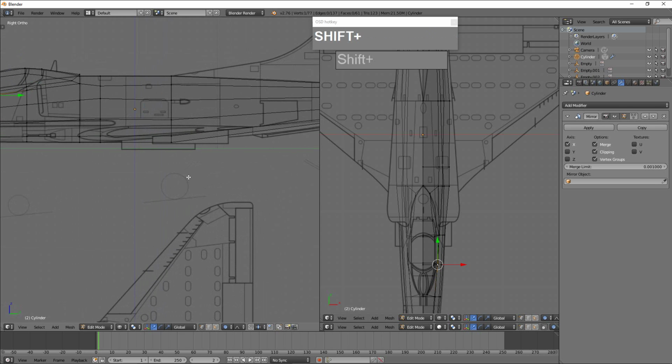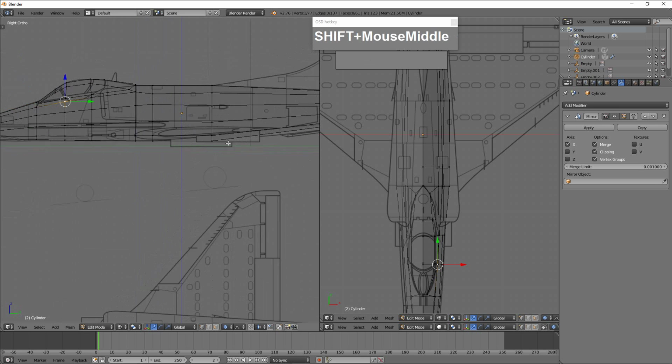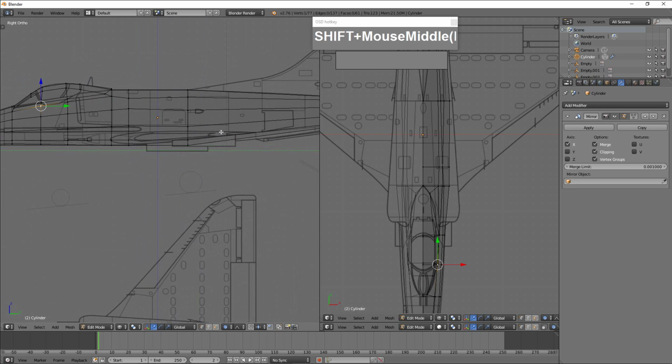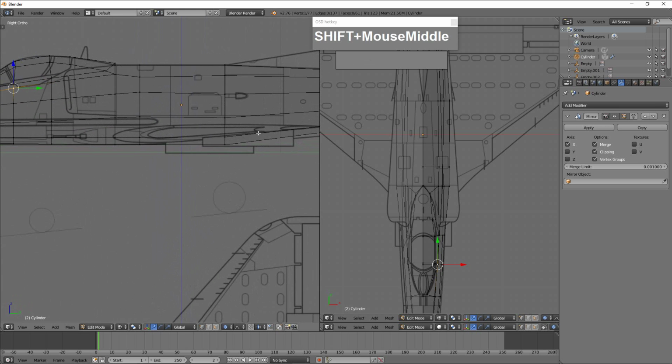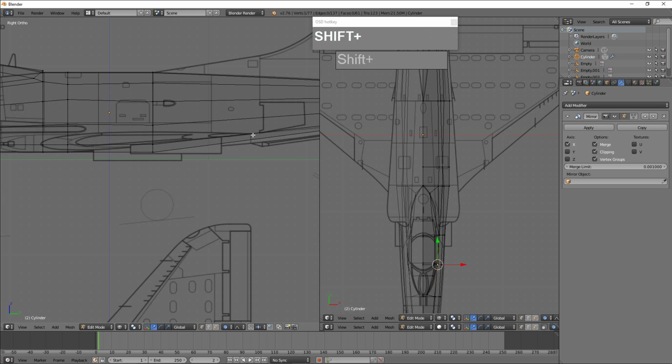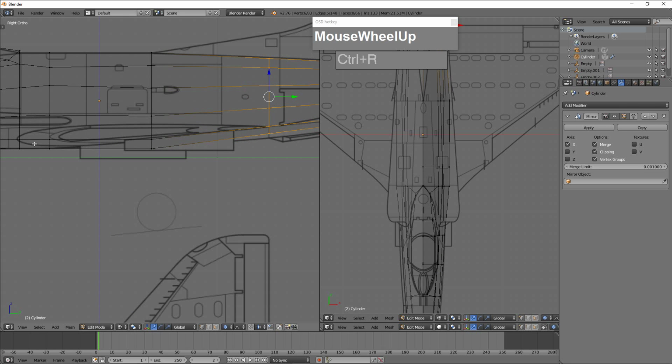Now the wing has a unique airfoil shape. So we will try our best to follow the shape so that we can pull out the wings. We know that the end of the wings ends here, so we need to insert one edge loop, Control R, and then insert one edge loop here. So this is where the wing ends, and we need a minimum of 1, 2, 3, 4, 5, 6 faces to pull out this wing.